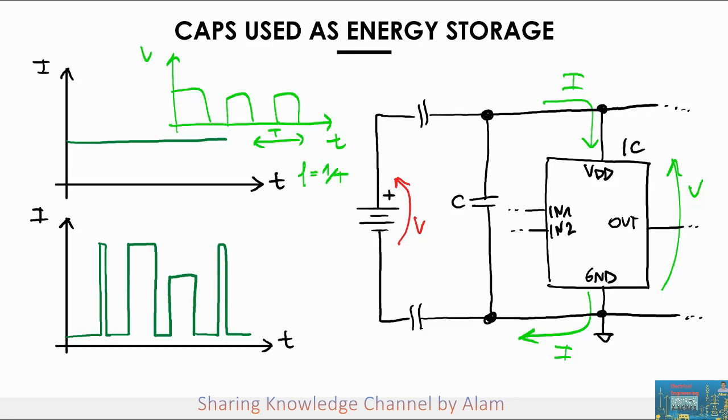Now, these pulses are used to synchronize the operation inside the CPU. So every time there is a pulse, let's say we could be on the rising edge of the pulse, like there, a bunch of operations are executed. And when the operations are done, no operation is executed until the next rising edge, for example. Operations inside the CPU are what requires a current. So if the CPU is sitting idle and not doing anything, you can assume that the current it requires will be really low. And that is the case. Most of the current is required when an operation needs to be executed, because that's when things move inside the CPU.